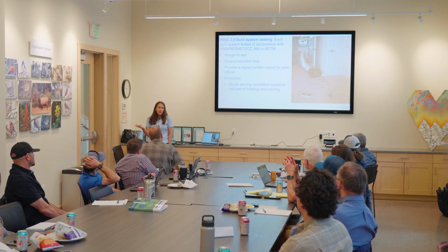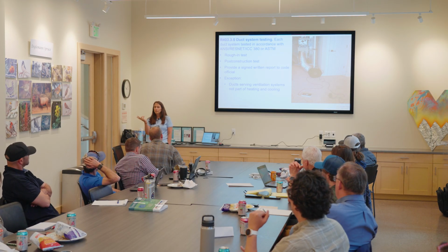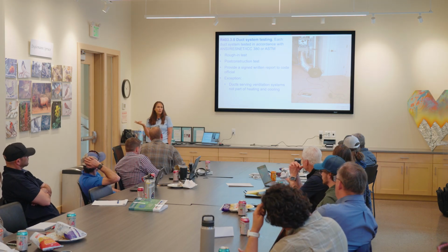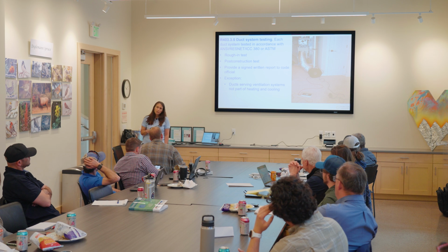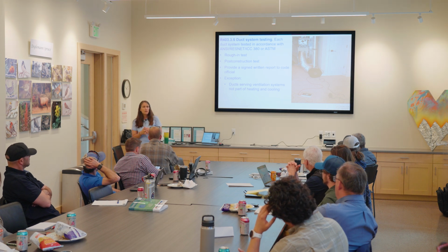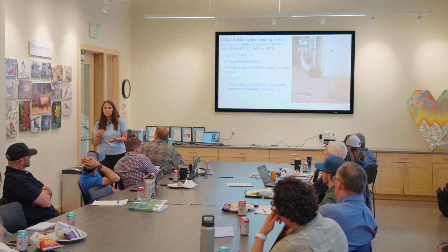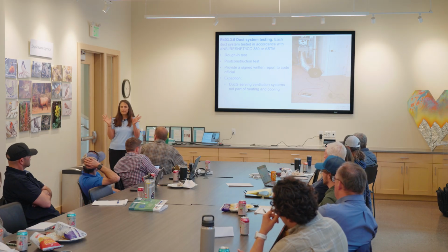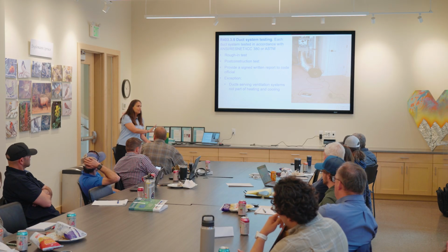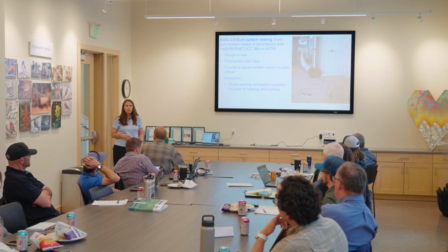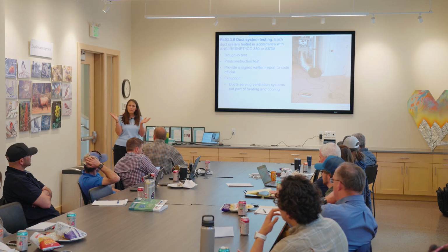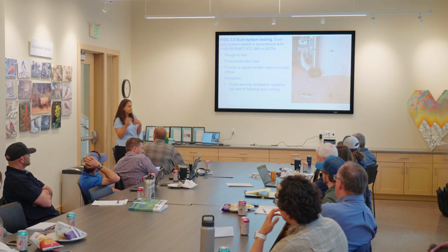Well, for all of you up here, you all have to have ERVs and HRVs, so they're doing a combination. As long as those ERVs and HRVs are not part of and integral to your heating and cooling system, that ductwork should never be tested. That system is there for ventilation. It has nothing to do with heating and cooling, even though technically heating and cooling is going on in that ERV, HRV type of deal.